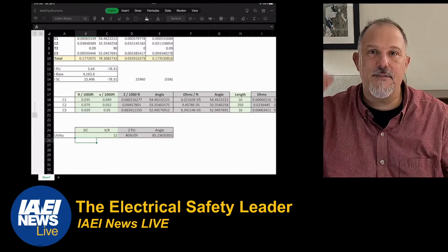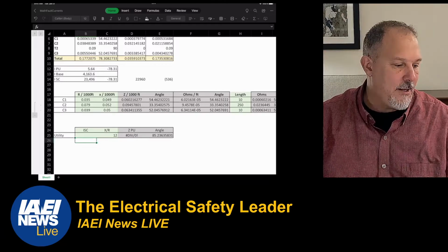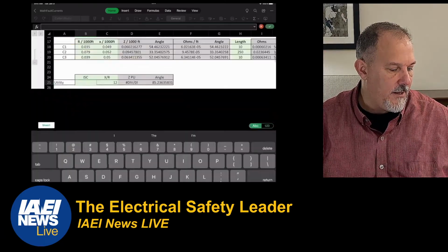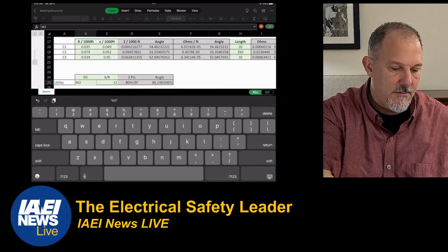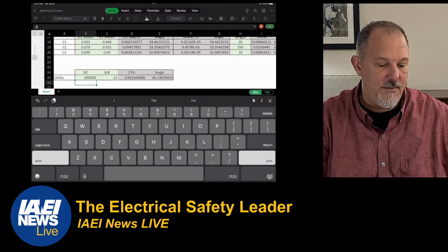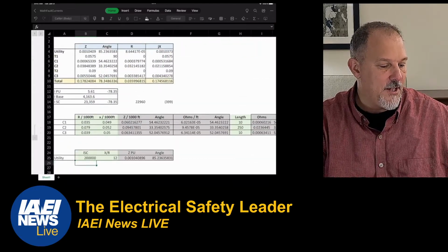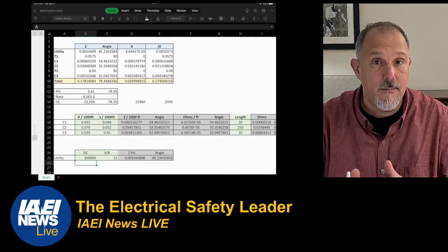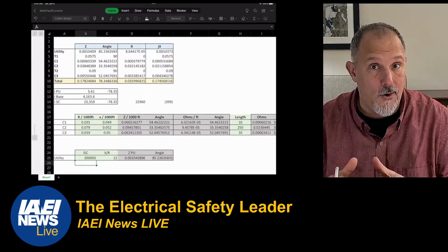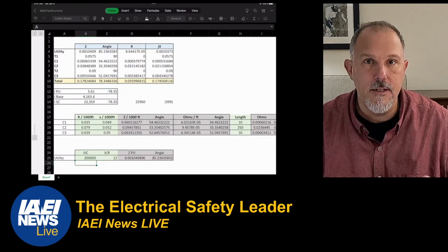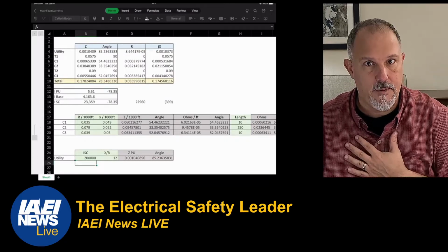Well, yeah, about 500 amps worth if the utility went from an infinite amount to, let's say, 200,000 amps. From 50,000 amps to an infinite was 300 and some amps, less than 400 amps. That's not much of a swing at all. And if you're picking your interrupting ratings within 399 amps, you got other problems, in my opinion.